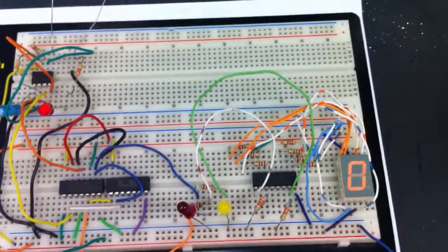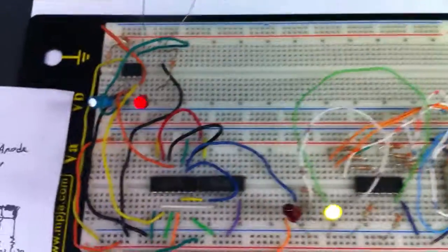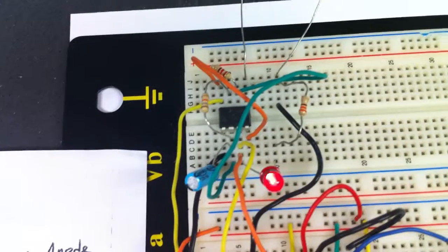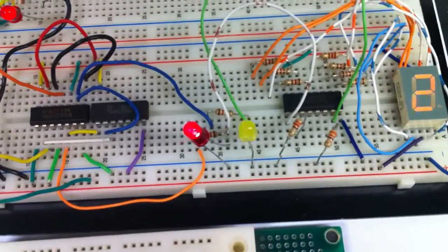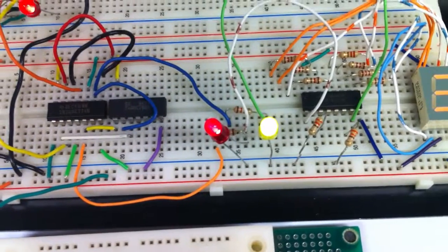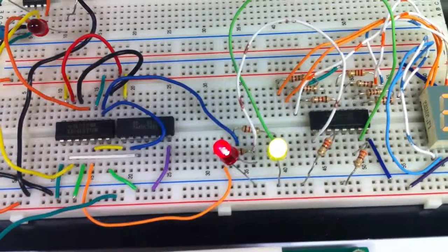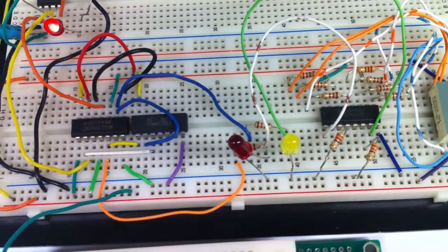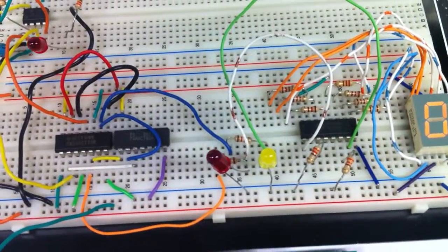See, look at this circuit working. This chip is a 555 timer. This LED indicates the output frequency. These two LEDs: the yellow LED is QB, the red LED is QA. The yellow LED follows the pattern 010101. The red LED follows the pattern 0011. See, sometimes it's not easy to observe this pattern.